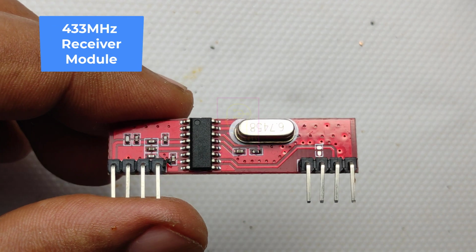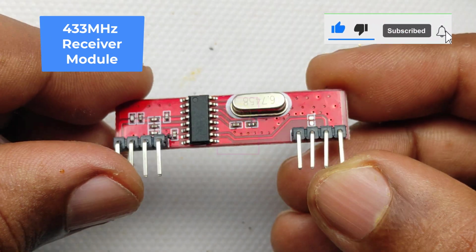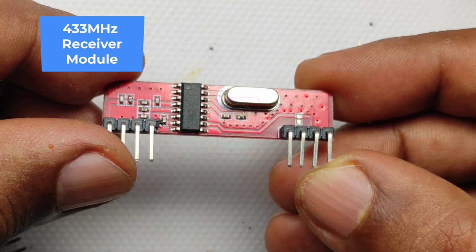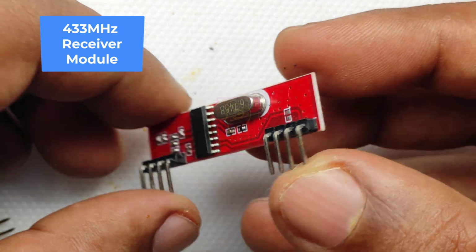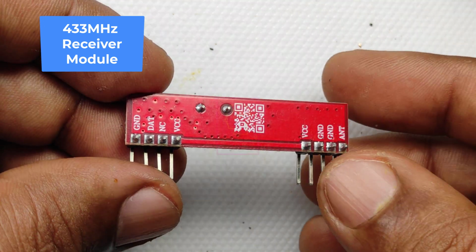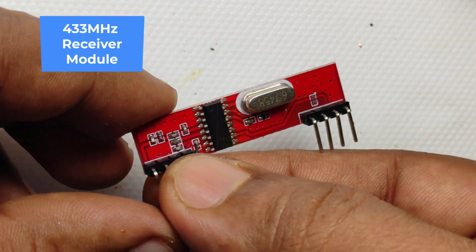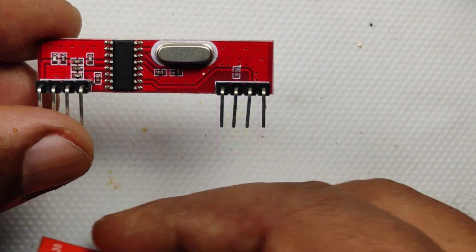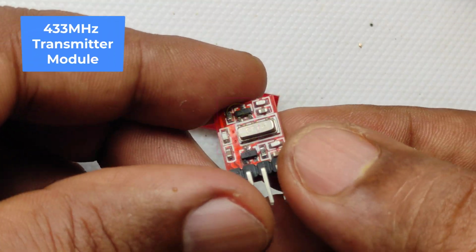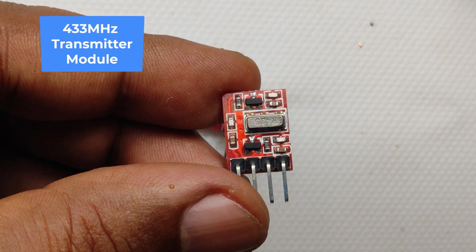This is RF transmitter and receiver module, which is working in 433 MHz. Whatever digital data we are giving into the transmitter will be transmitted and received by the receiver module. This module is using ASK or amplitude shift keying technique. ASK is a type of amplitude modulation which represents the binary data in the form of variation in the amplitude of the signal. Since this is using amplitude modulation, the range of this module is high.